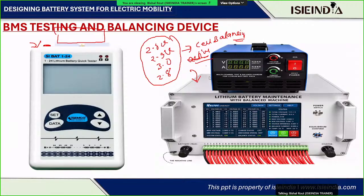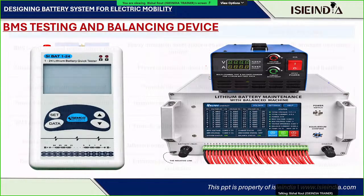Basically, in active cell balancing, the higher voltage is transferred to the lower cell. But in passive cell balancing, the cells that have a higher voltage get that voltage dissipated. So this is a lithium-ion battery pack balancing unit. Before testing the pack in the actual testing machine, you first have to balance the cells over here. Once the cells are balanced, you can take the battery pack to be tested at the other end.